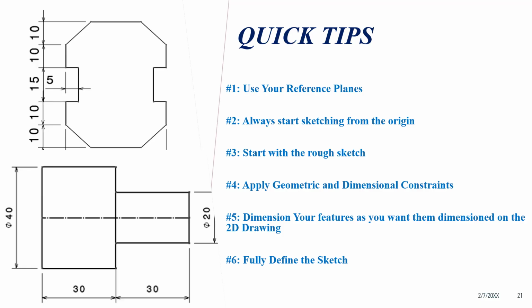Here are some quick tips before getting into the Sketch Workbench. The first thing is to use your references or the reference planes as much as possible. So while starting any of the Sketch Workbench, try to utilize the planes. If you're dealing with the features also, it is better to utilize the planes. So always start sketching from the origin. That is the best way to start your sketches, because from that you can reduce your geometrical and dimensional constraints.